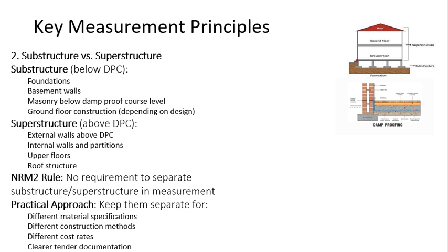So that means what? I can make the BOQ of the entire masonry from under the ground till the top floor as one quantity, unless you have a change. Maybe there is a change in material. The masonry under the ground is a different material, over the ground is different. Maybe the external wall is different, the internal wall is different. So if you have a material change, then obviously you will make two BOQ items. Or you have a different construction method. Here you are using solid blocks, here you are using cavity wall. So the construction method is different, obviously the BOQ item will be different.